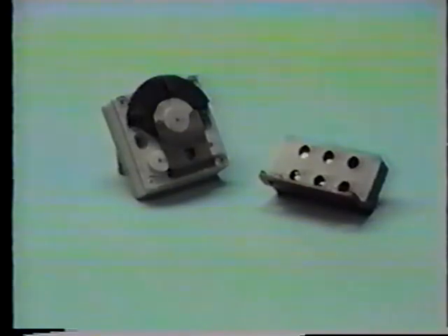Another type of thermostat found in the field is the unit ventilator thermostat. This thermostat is designed to mount inside the cabinet of a unit ventilator. This Robert Shaw device utilizes a remote bimetal sensing element that is mounted in the return airstream.